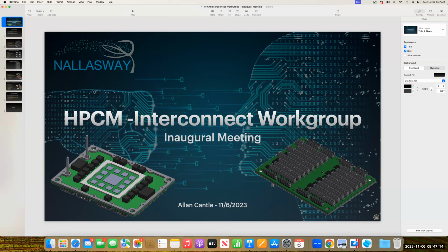Well, there are other groups doing chiplet stuff. I'm looking at the chiplet thing, and okay, I've got a pile of stuff in an interposer. Can I glue my interposer to a connector like this? I'm not thinking that works well. If I could just slot my interposer in and it connects capacitively, mostly, then that might work. But it's not been addressed that much in the chiplet group.